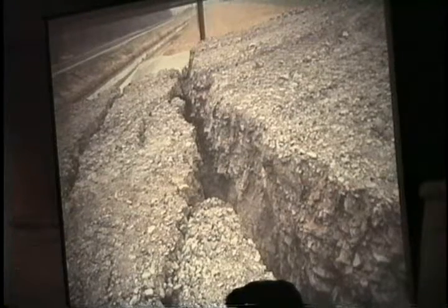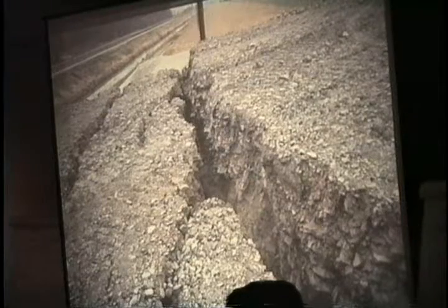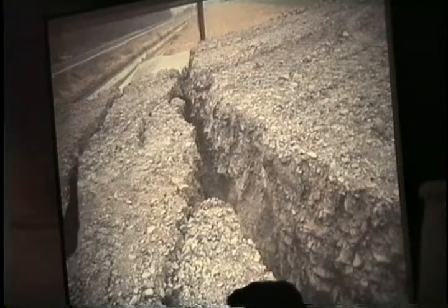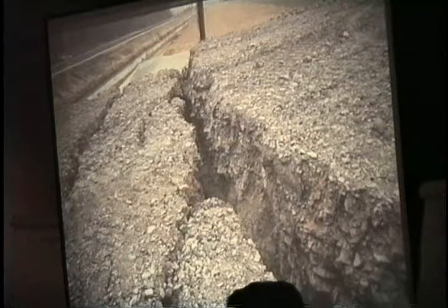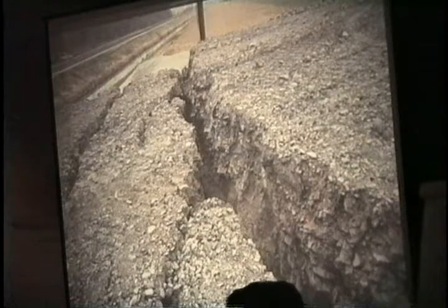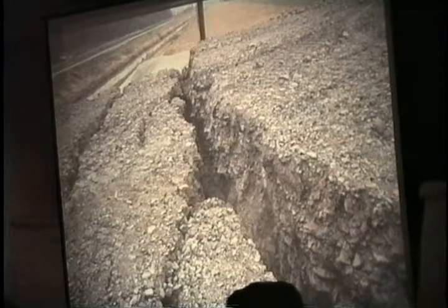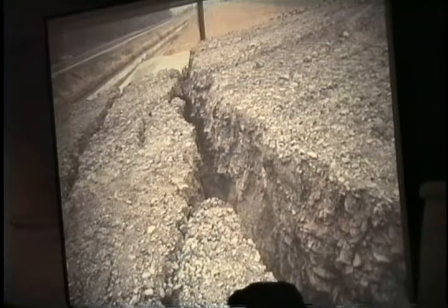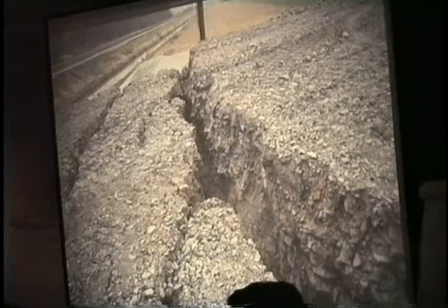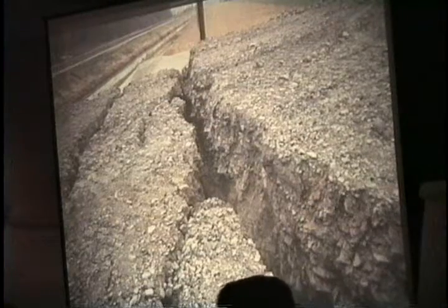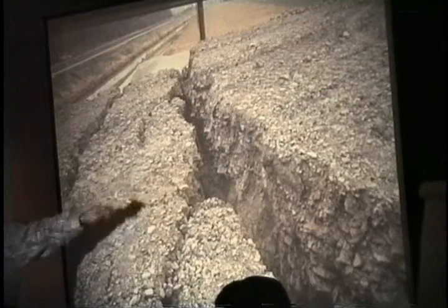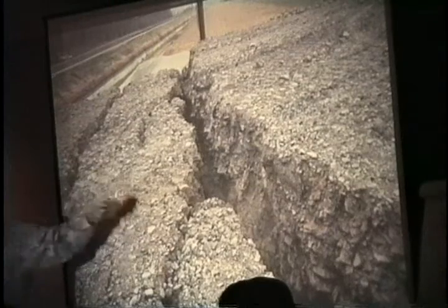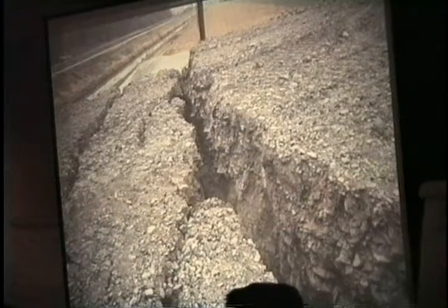So I said to Gordon, okay, here's the sketch. I call him Gordon because that was his name, but he's retired, so he's a good guy. He was involved in the project, and he was panicking because this thing looked like it was moving fast. What should I do? I said, Gordon, come in back of the wall about 30 feet, put in some scrapers, which were on the job, and unload this approach embankment.